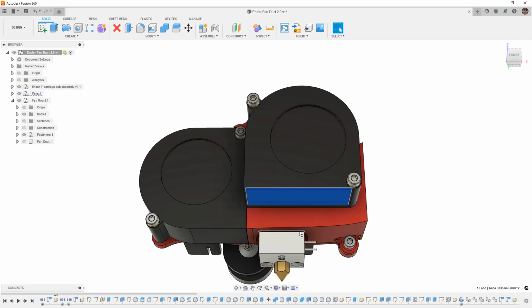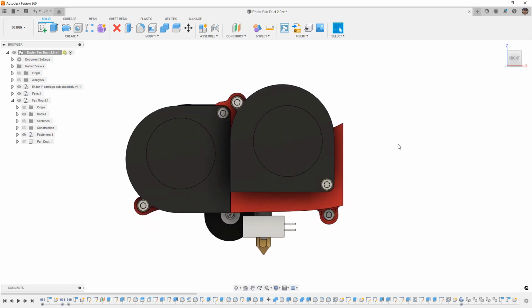Now, when we're starting a design like this, there are two main approaches that we have to think about, and these are independent of whether you're solid modeling or surface modeling or form modeling. That's going to be, are we going to build the inside volume of the part, or are we going to build the outside of the part? In a case like this, I would opt toward building out the actual inside volume as a solid body that can be cut away from some other shape.